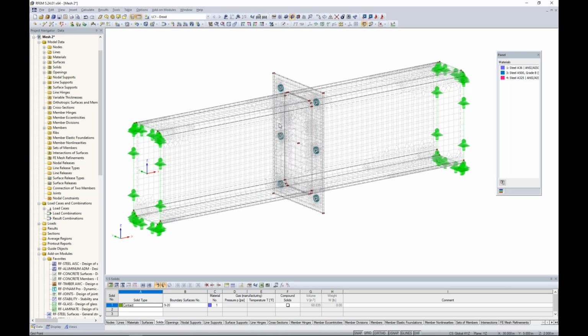So this is going to be the ideal mesh to continue moving forward with our static analysis. So again, you can either manually set that global mesh and add in your own FE mesh refinements if you'd like a little bit more control over it, or you can utilize this adaptive mesh refinement within the program to have the automatic mesh set for you.